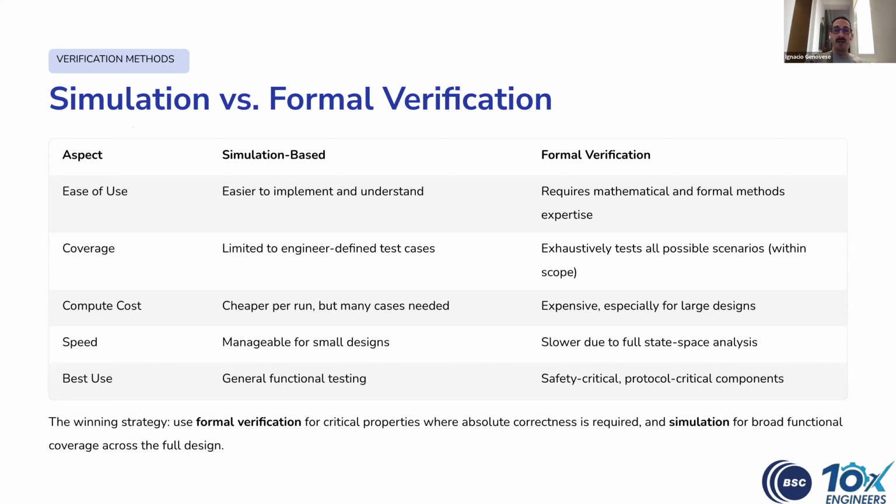And formal is expensive, especially for large designs, because it needs a lot of computing power. Regarding speed, simulation is manageable for small designs, and formal is slower due to full state space analysis.